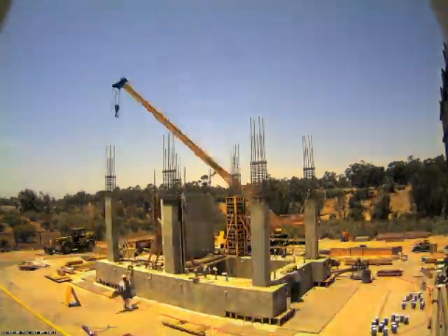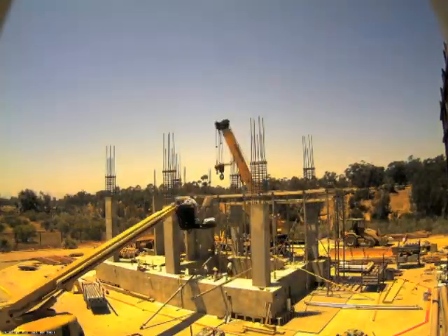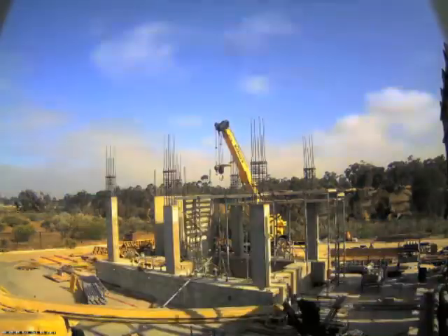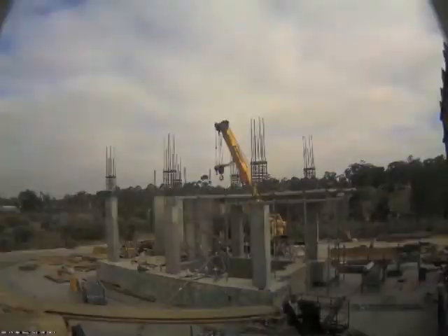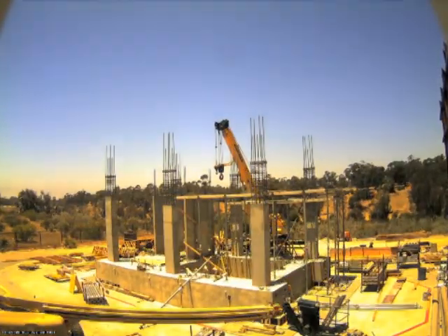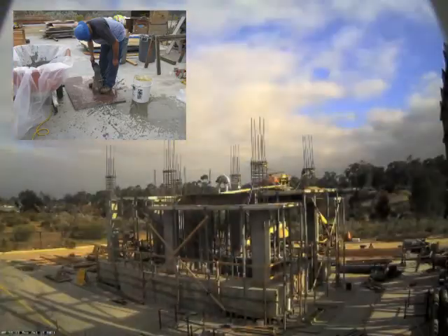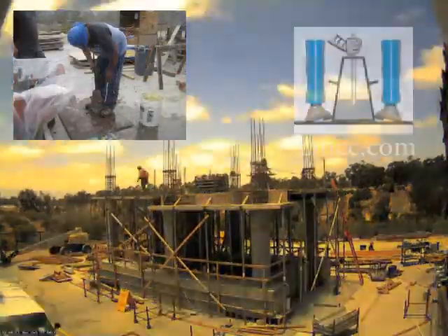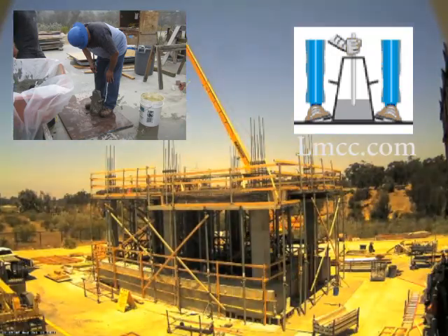Every time concrete is poured during a construction job, several standard tests are conducted to verify the expected workability and strength of the concrete mix that is delivered to the site. For each concrete truck that arrives on site, a slump test is performed immediately on the side of the job site. A cone-shaped mould is first filled with wet concrete. Then a metal rod is inserted into the top of the cone and pumped up and down 25 times. This helps eliminate air bubbles and increases the homogeneity of the concrete mix.